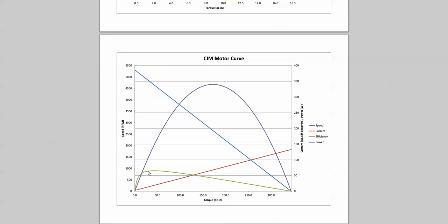So then if you look over here at peak efficiency, which is about here, your power is not very high. I guess this purple line has the power units on the right, so you can see peak power on a sim. Mechanical is like 340 watts, 330, somewhere around there. And the power at peak efficiency is a little over 100 watts. Now, that 100 watts is still a fair amount of power for doing something, but certainly 3 times power is better. Because you are operating at this high efficiency point where you're not making a bunch of heat, because that's where the electrical power that isn't going to mechanical power goes, you can operate in this range for a much longer period of time. You could easily operate the entire match here, and I don't know the exact cutoff for the sim or any other motor. I have some gut feels, I just don't want to say those and lead people the wrong direction.